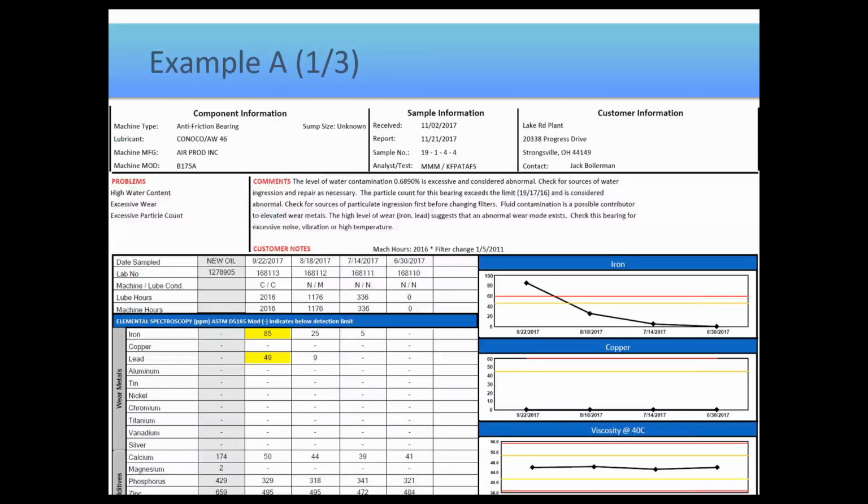And the answer is, if you fixed it, if that truly corrected the issue, the next result should look about the same. It won't look better unless there's significant filtration on the system that might help remove some of the particulate that's in there. But what is there is there. The wear that has happened is not going to go away. The particulate that is in there is not going to go away. The water that got in is not likely to exit much. So you're going to get very similar results, not lower results. Some people think it'll get a lot better if you fix the problem. Well, no, because all you did was stop the problem. You didn't reverse the problem.